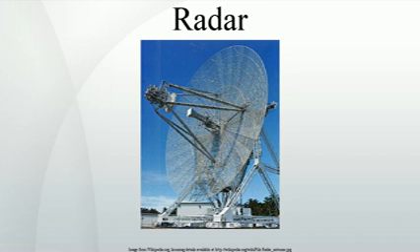The distance resolution and the characteristics of the received signal as compared to noise depend on the shape of the pulse. The pulse is often modulated to achieve better performance using a technique known as pulse compression. Distance may also be measured as a function of time. The radar mile is the amount of time it takes for a radar pulse to travel 1 nautical mile, reflect off a target, and return to the radar antenna.